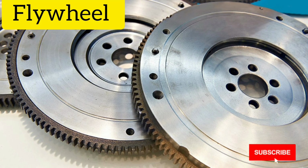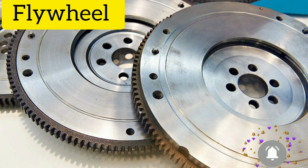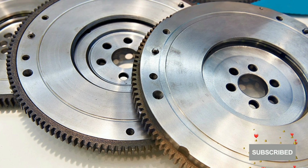This is a flywheel, and this component is connected to the crankshaft. The flywheel provides the mounting surface for the clutch system. This is where the clutch system is connected. A clutch system receives engine torque via the flywheel, and this is a hole on the flywheel. This is where the crankshaft bolts are connected, and these are the pins you are seeing on the flywheel. This is where the clutch cover assembly is tightened.